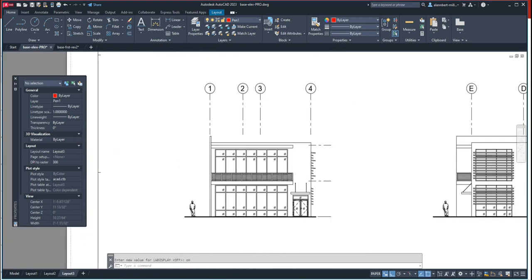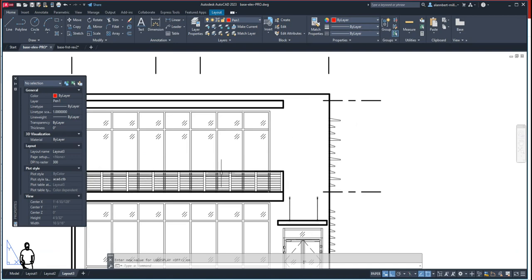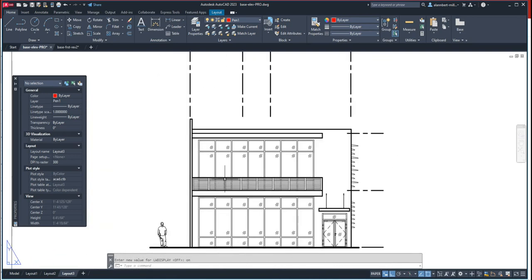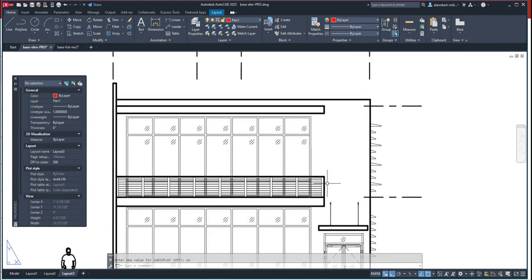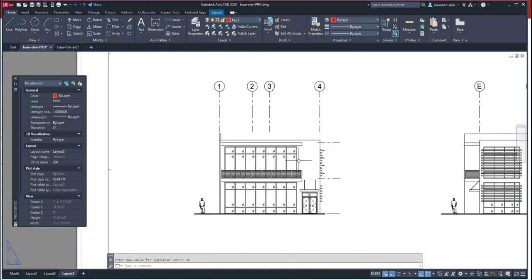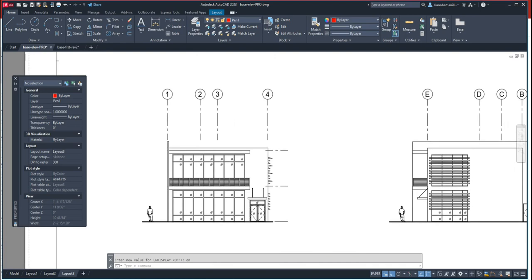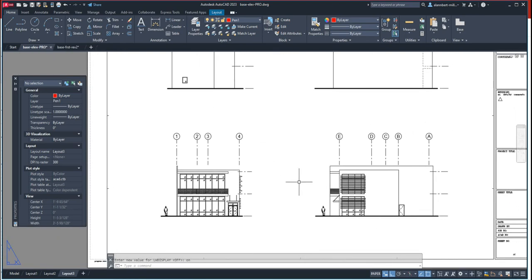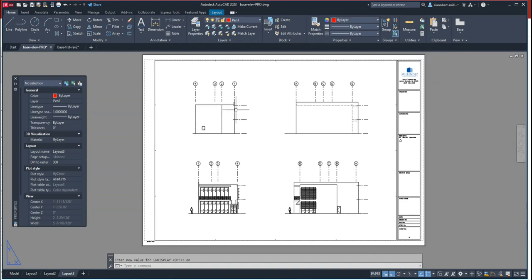Sometimes people don't like to see it this way because they don't know what color assignments have been assigned. They just know that it's thick, but they don't know which color would make this drawing this thick. Anyway, we have done our color assignments now, and we are now setting this up for printing. So we can now put in drawing titles. At this point, we can apply our plot styles and turn line weight display on. Let's now work on the titles over here.